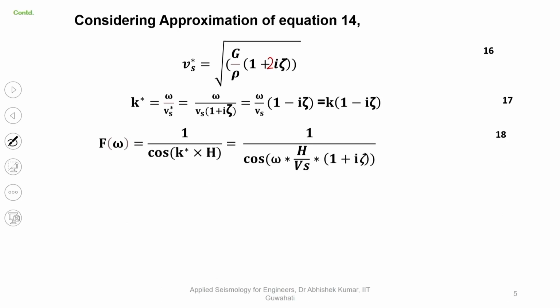The transfer function is going to give you the ratio of displacement between the top of the soil layer and the bottom of this particular soil layer, because we are considering the thickness of the soil layer as the entire thickness, value equals z or h. Then for the transfer function, you find the value of u corresponding to z equals 0 and corresponding to z equals h. Take those two in ratio, as discussed for the undamped case, and we get the transfer function. Remember, for the undamped case, the value of the transfer function was 1 over cos of k h. That was the value of the transfer function for the undamped soil.